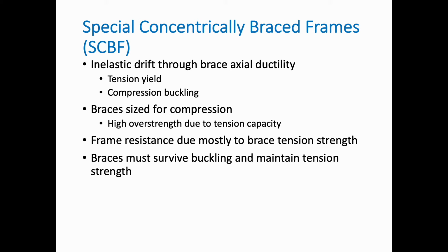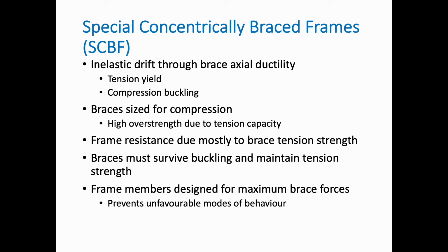That will lead to the failure of that member. But if the plastic hinge is formed in a controlled manner, then that's absolutely fine. In the reversed load, the same member will be subjected to tension, and if the tensile capacity is not really affected by its previous state being in compression, then we have a perfect design. So frame members are designed for maximum brace forces, of course, and that prevents unfavorable modes of failure, as we'll see in the next few slides.